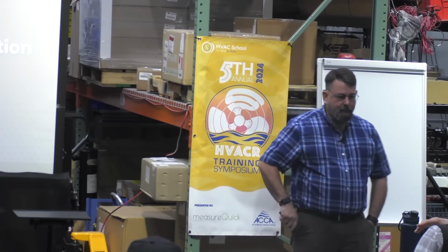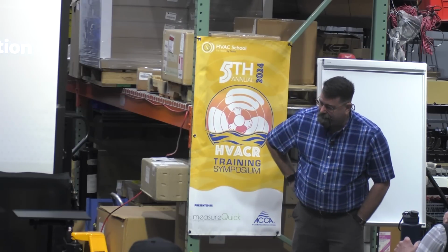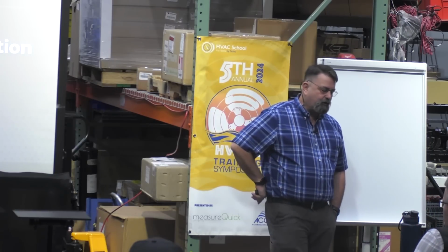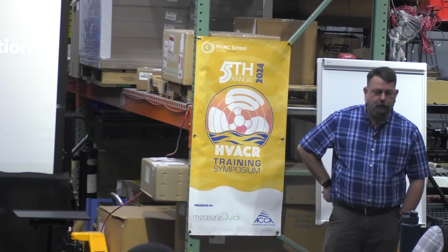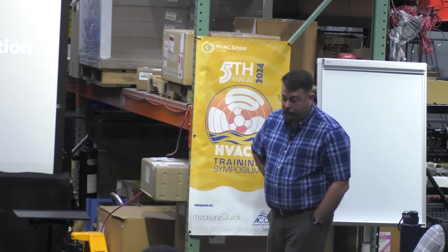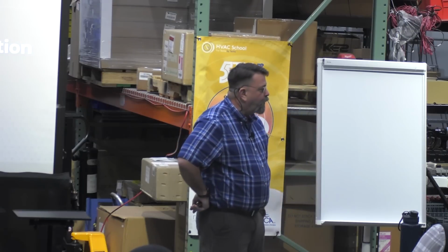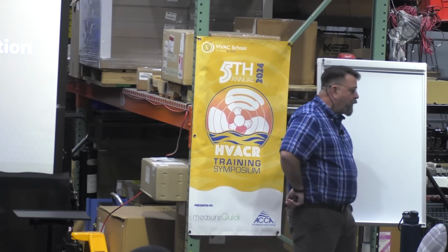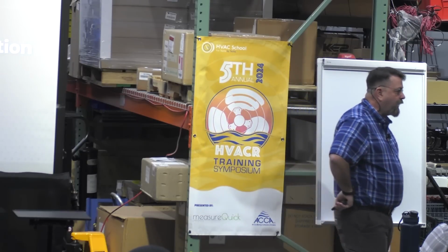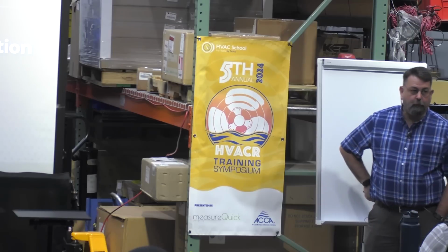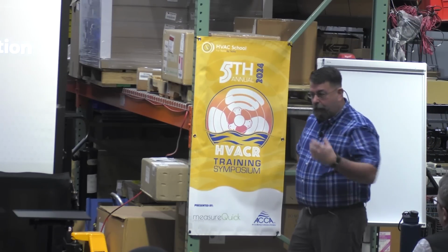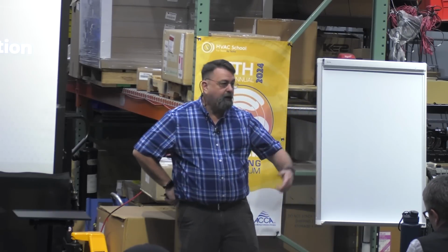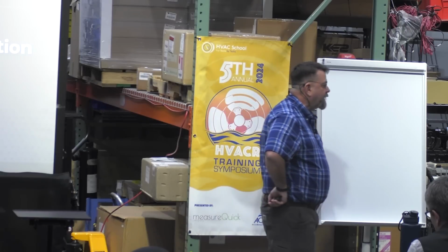Suction line dryer, would that be upstream of the accumulator and could possibly have liquid go through it, or does that need to be on the vapor side? So it's traditionally upstream, right? So if you do have liquid right before it hits the accumulator, it would go through that, right? Now, we can use a dryer in there. Most of the time, it's just a filter, honestly. The only time we would run an actual dryer in that is if we had moisture problems and we were actually trying to absorb that moisture and change them out until they come out dry. That idea, a cleanup, right?